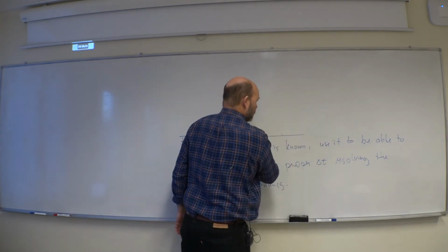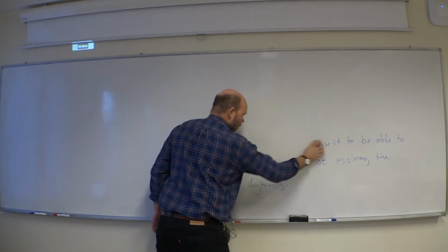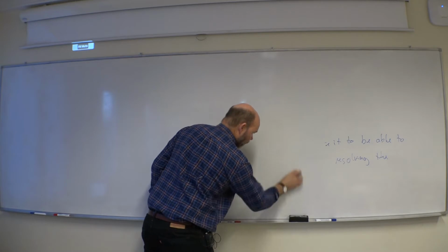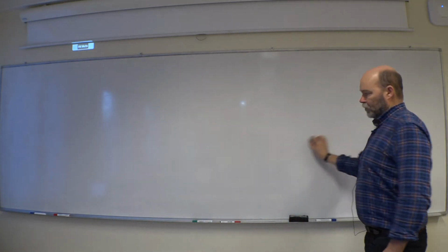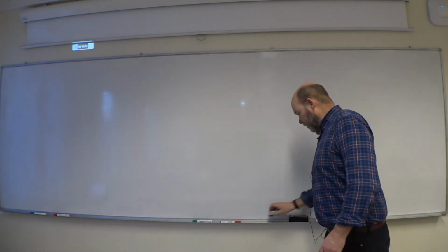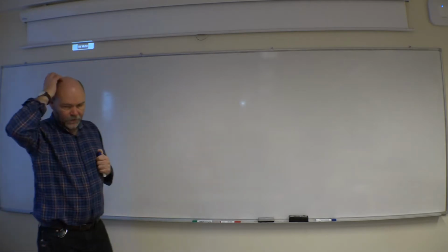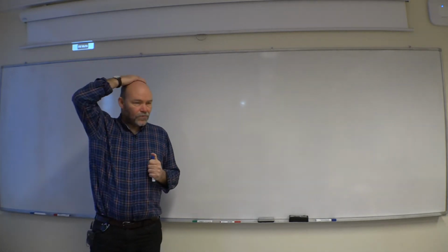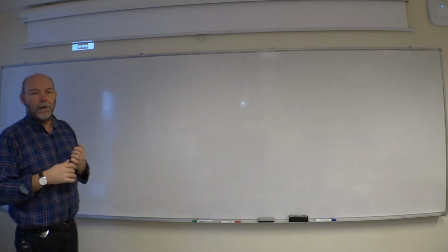So they should be easily found. So then you might argue you don't have to rewrite the Navier-Stokes to get them on a non-dimensional form. If you know the Strouhal number, then you can of course find the time scale in seconds, and then you can choose a proper delta t in seconds if necessary for one particular problem. So that's okay.